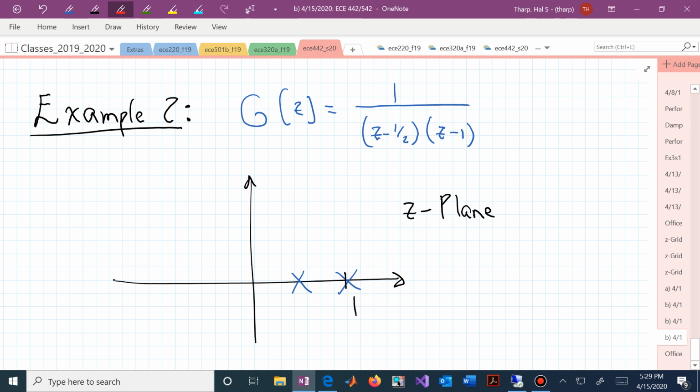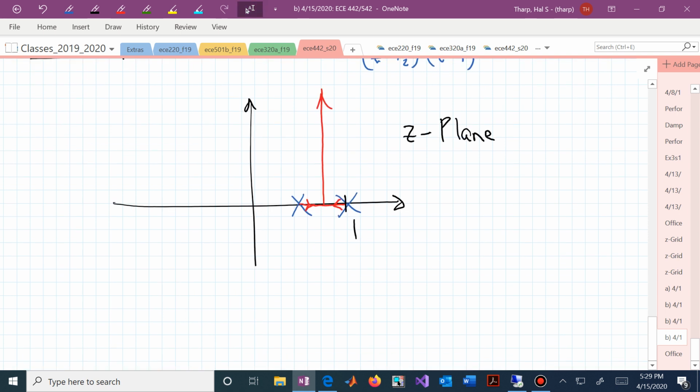You can subdivide the real line into 3 segments, and I hope that you see that in that segment we have one pole to the right of that segment. This pole goes to the right, this pole goes to the left. We have 2 branches, we have 2 closed loop poles. Those can't just terminate, they now move away from each other in a manner that splits the z-plane.